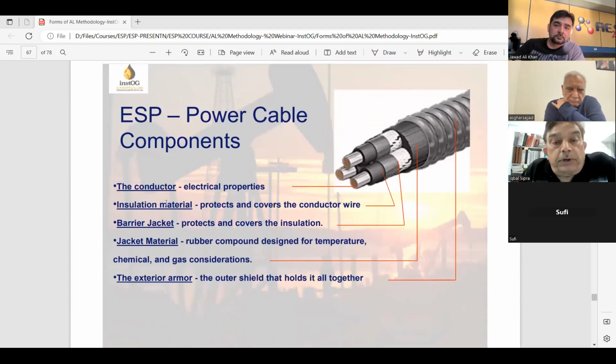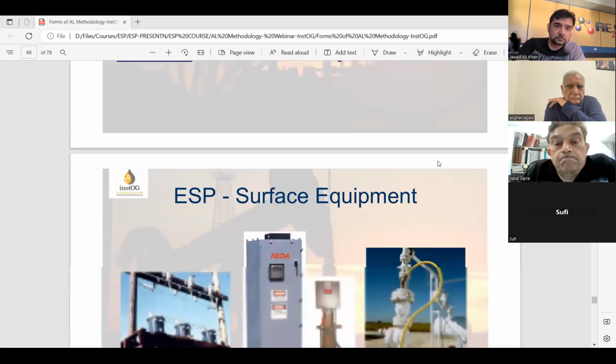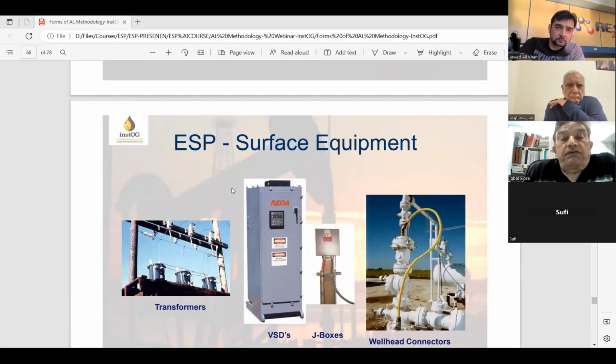ESP power cable components: first of all is the conductor, then the insulation material, then a barrier jacket, then a chemical and gas protector, and then your mechanical armor. These are your surface equipment: your transformers, VSDs, junction boxes, and the wellhead.